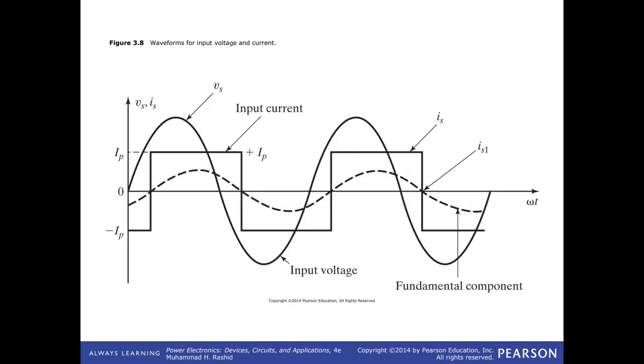That is input power, input side, input current, this one. For the flat top waveform, I analyzed that waveform with Fourier analysis, and I showed that we have odd harmonics. In Turkish, tek sayı harmonikler: 1, 3, 5, 7, 9, 11, 13.